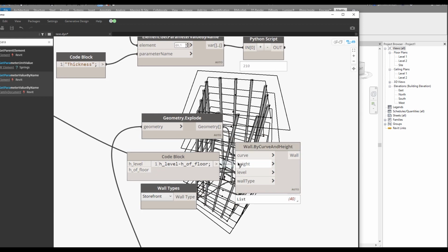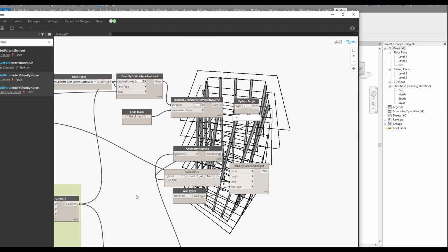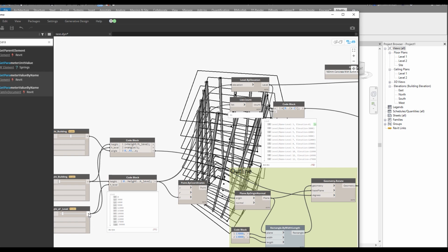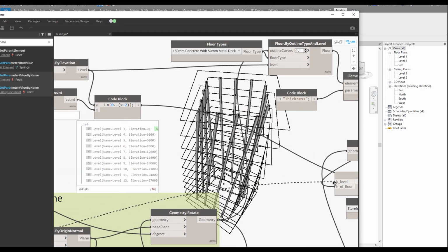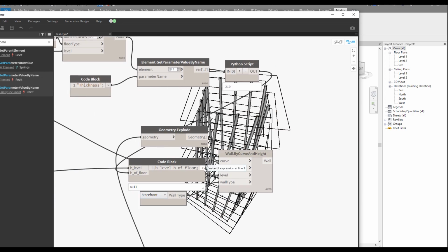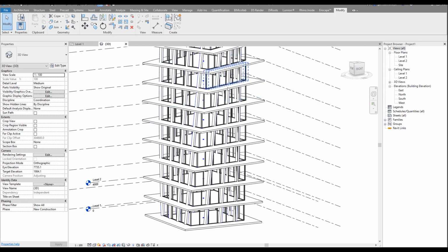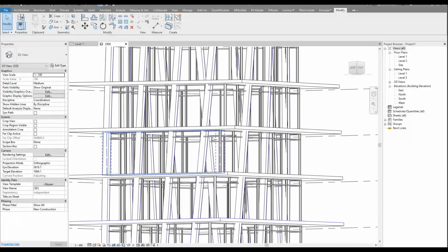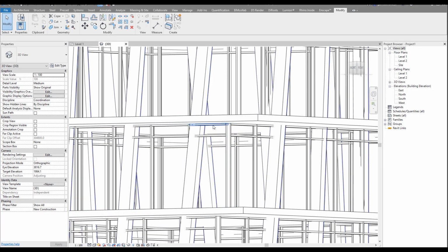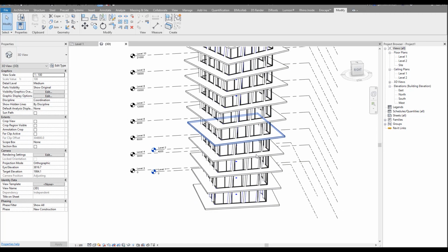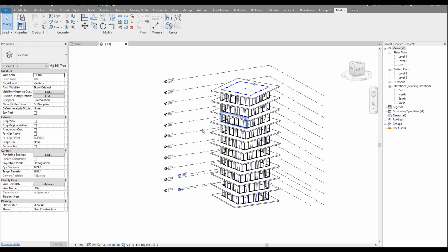Now we should connect height to the floor, and height from the level, it's here, to the level. And this one we should connect to the height. Let's run it. Now everything will be alright, 100% sure. And as you can see, now everything is alright. And as you can see, the mullion is exactly under the floor. So we already finished. You now have a really awesome script.